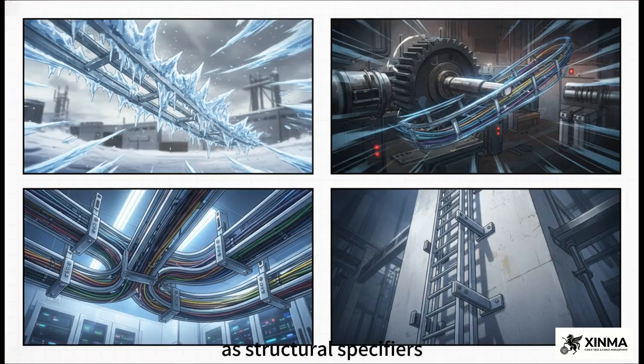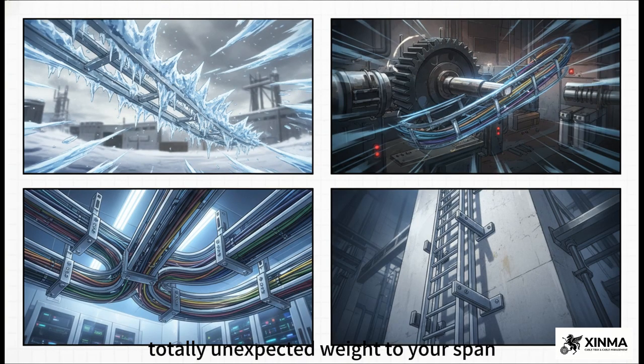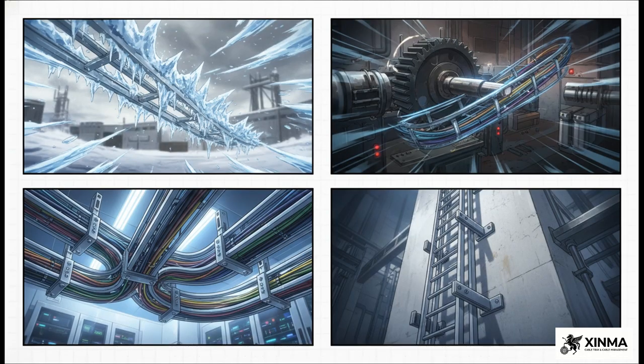As structural specifiers, we know full well that the environment always gets a vote. Outdoor runs introduce wind loads and ice accumulation. That adds massive, totally unexpected weight to your span. Heavy mechanical vibration from nearby machinery can cause severe fatigue over time if your supports are spaced too far apart. Complex fittings change the load distribution entirely, and vertical drops require completely different bracing strategies. Any single one of these factors will immediately force us to overhaul our baseline support plan.